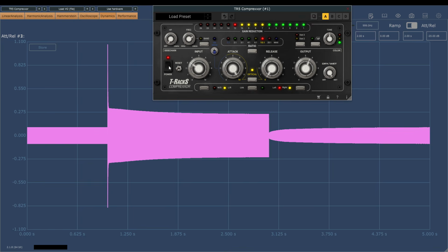So here's the compressor response. Notice the powerful spike before the attack clamps down on the leading edge of that loud section. And the way the rest of the loud section continues to ramp down in level, as if a portion of the attack stage is much slower and is still responding a full second after the level change.